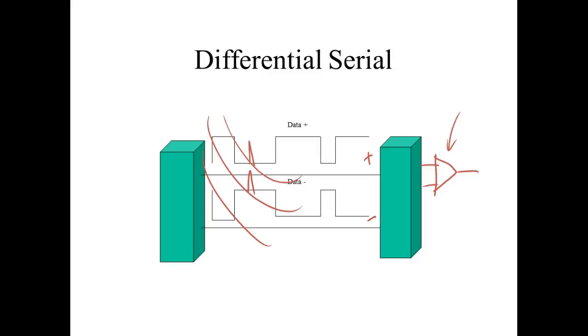That's not because of common mode. It's because if lightning got into one of the cables, it would blow up these differential amplifiers. So normally when we go outside, we're supposed to use fiber optics. So we got fiber optic cable lines from here to the buildings.